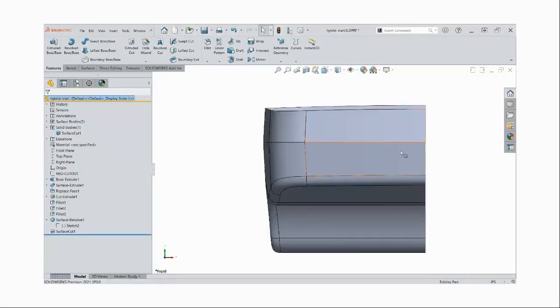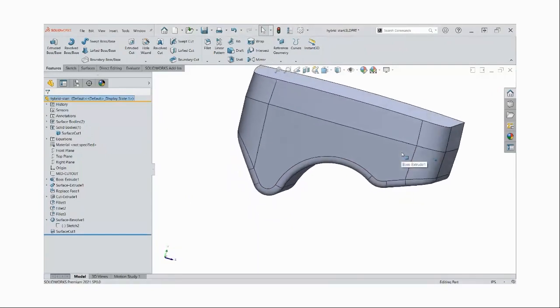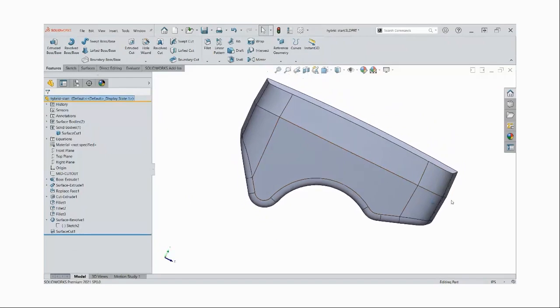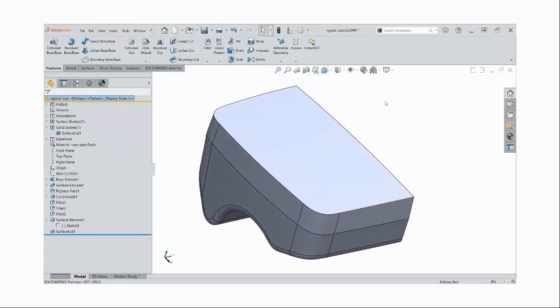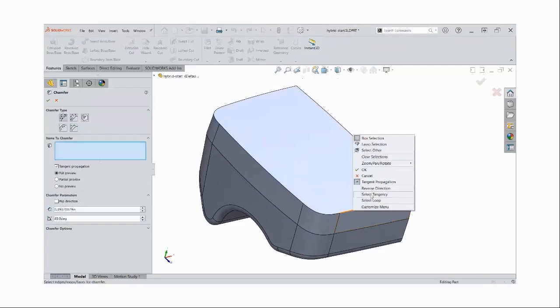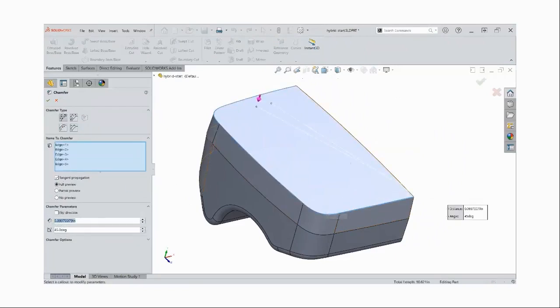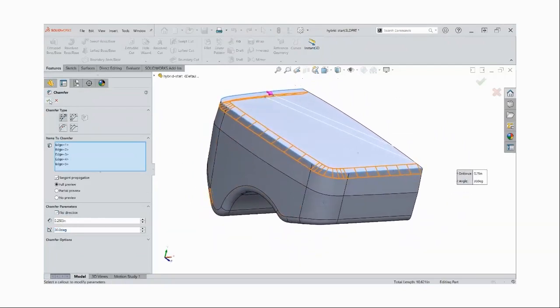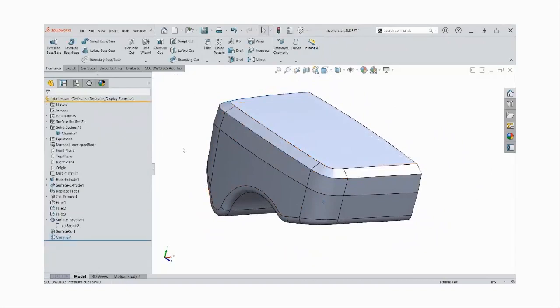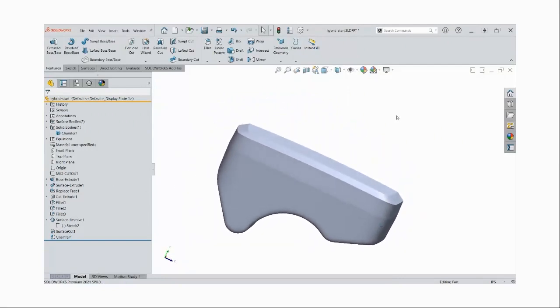Okay, so if we look at some of our standard views, you'll see that now it's curved in kind of every direction. And those other enclosures had some big heavy chamfers around them. So that's going to be one of my last details here, chamfer. And I'll just right click, select tangency around this set of edges, and set a chamfer here. And I'll set this to be pretty shallow, kind of emulate that appearance that I want.